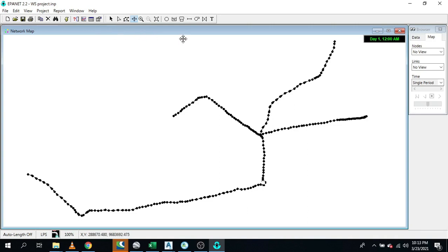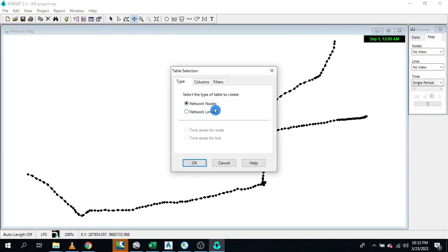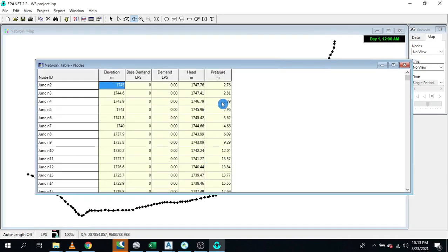Again, report you can produce with several ways. So for me, I'll go here to reports, select no, just before that you can select here and look at nodes. So let's say nodes. Within nodes, we don't need quality and elevation. We want elevation, then select OK. So you can see all of your node here with pressures. Okay, so all of these are your nodes. Again, these are the pressure.